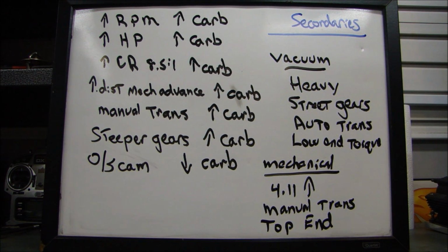The type of distributor will just determine what kind of carburetor you need, because you need to know whether or not it has, with or without the vacuum canister, ignition box, if you're going to have a dual or single plane manifold, and the exhaust. Don't forget about the exhaust, the tube size. If you're going to have headers, what's the tube size? You know, is it a 1 3/8, 1 1/2? The tube size is also going to have an effect on the choice of the carburetor you have.